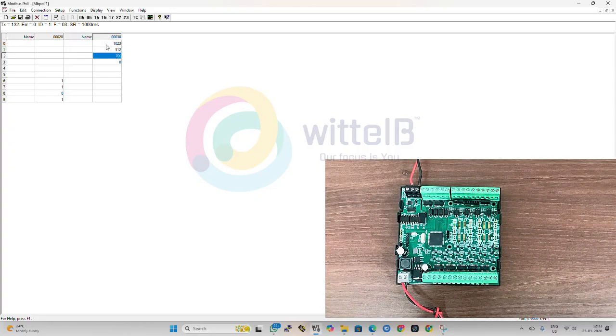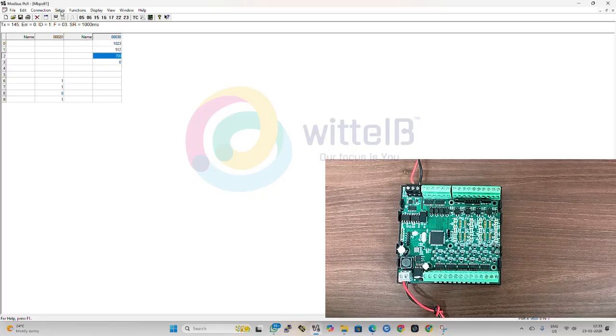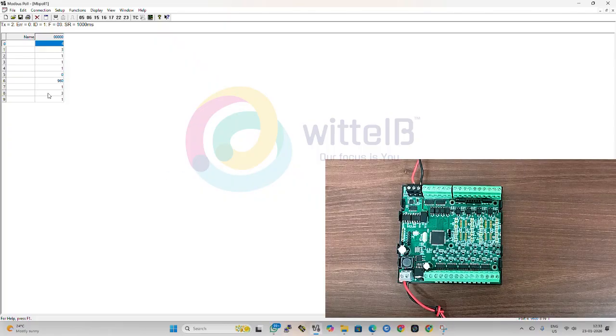You can configure UI and UO at any time as per the requirement, but for the UI channels from channel 9 to 16 it will be DI as default. Go to the registers and change the address. Here you can configure anytime for the UI and UO.